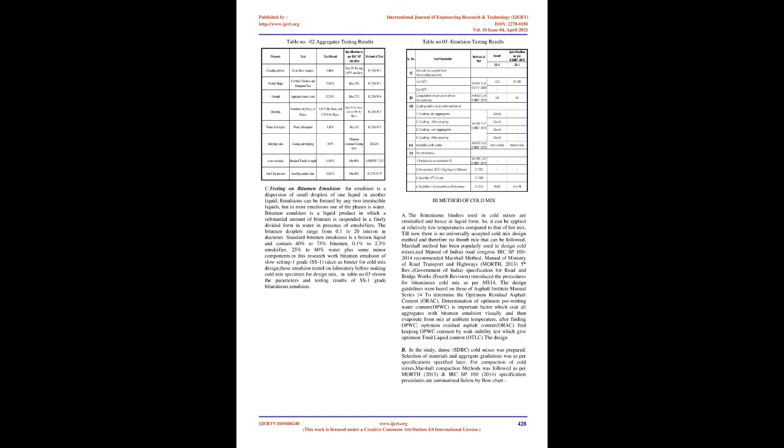2. Material used. A. Aggregates. Black basalt aggregates of 20 mm and 10 mm used as coarse aggregates, crushed sand as fine aggregates, and lime as filler. Following are the sources of materials. Table No. 01. B. Testing on aggregates before conducting cold mix design. Material suitability is checked, then mix design conducted. Following testing conducted on aggregates.